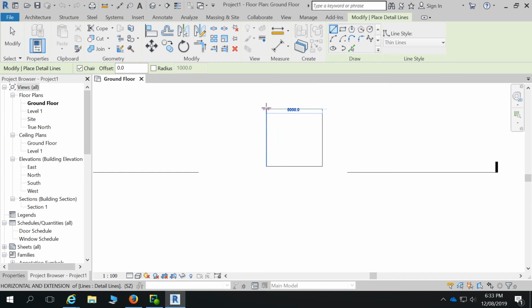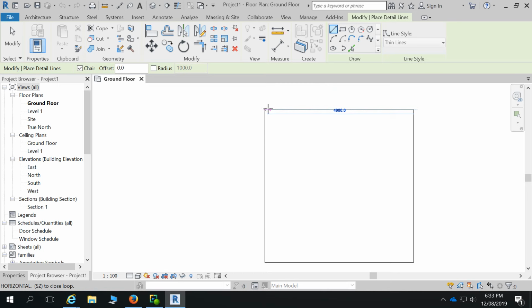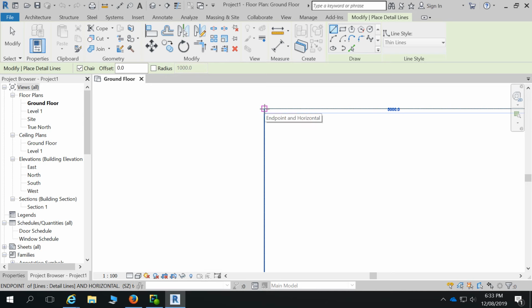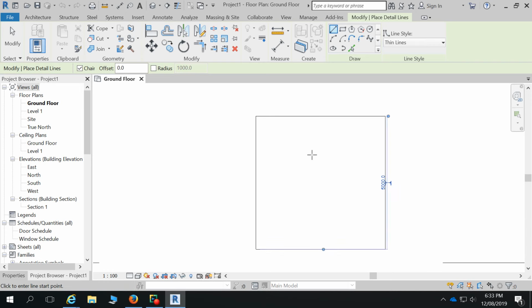And then we'll go back over and we'll snap on the original point. If you zoom in a little bit, put your cursor over the place that you want to zoom and use your scroll wheel, you'll see that it comes back and you get a little snap end point. Does everyone find when they got to the end they get a little pink square? That's known as a snap icon. That snap icon means it's hitting the end point. Same in AutoCAD, you get endpoint snaps, and we can just click there, so we know it's quite accurate.